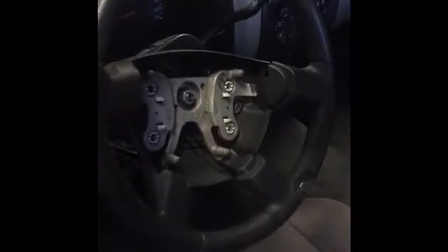A rack and pinion system is a little bit more responsive and a little bit better off than a parallelogram system, and it's honestly all about preference. As you can see on this vehicle, we have the steering wheel, which is connected to the steering column, which runs down to the steering box, which is on the other side of the firewall. And what that does is it converts the rotary motion of the steering wheel to the linear motion needed to pivot each of the wheels.